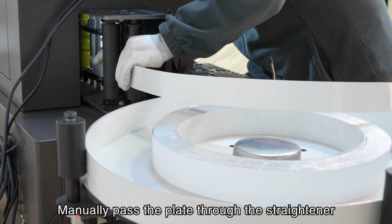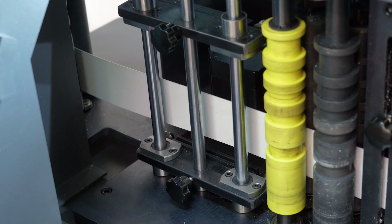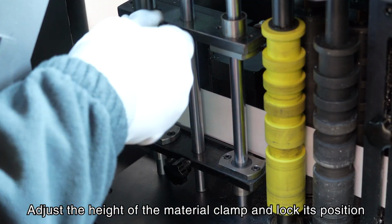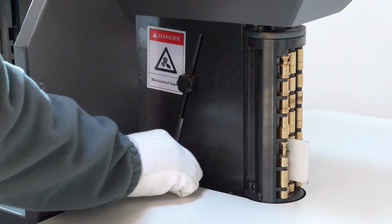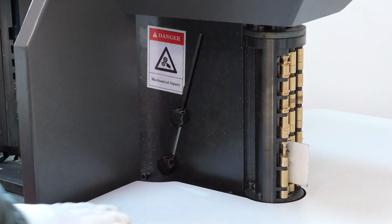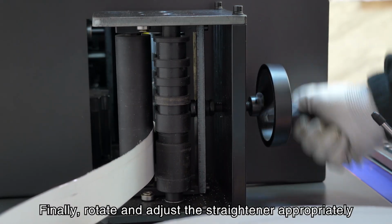First, put in the materials. Manually pass the plate through the straightener until the bending outlet, ensuring smooth flow. Adjust the height of the material clamp and lock its position. Finally, rotate and adjust the straightener appropriately.